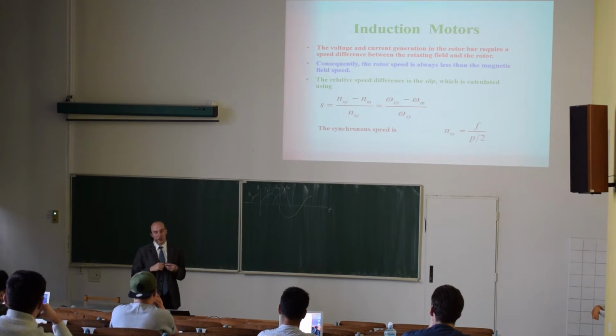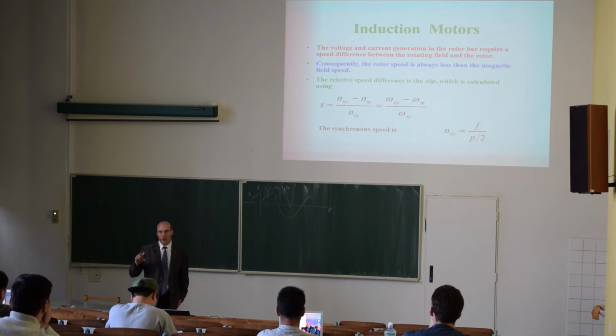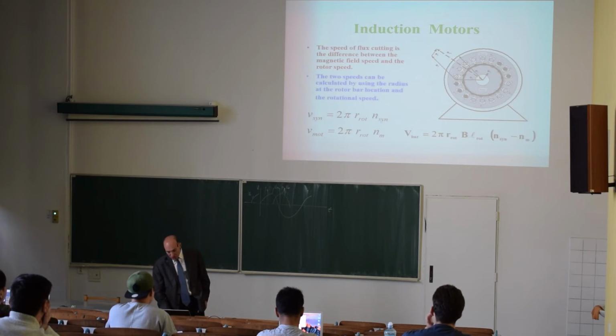No, the synchronous speed depends only on the frequency of the voltage, not on the amplitude. So here, the synchronous speed is given by the frequency, that's here, and by the construction of the motor, where P is the number of pole pairs in the motor.